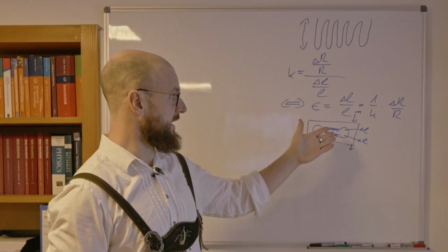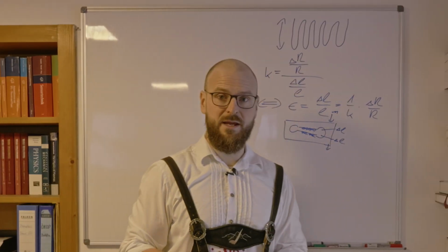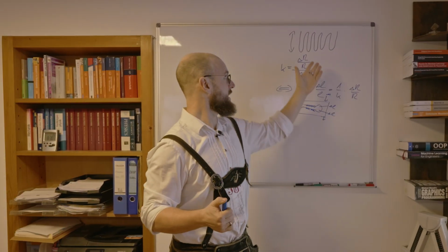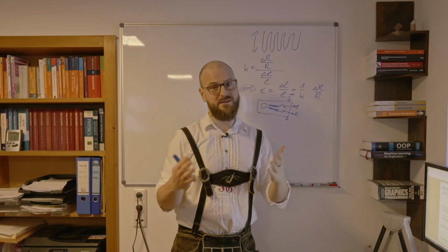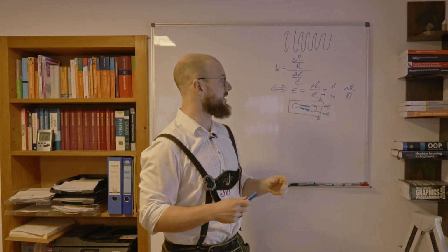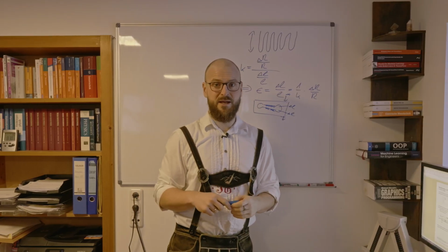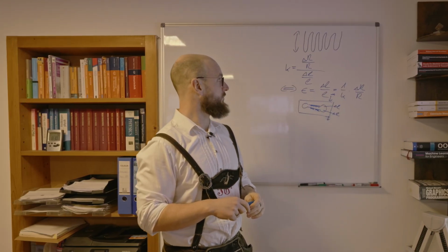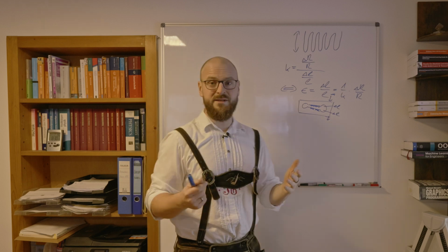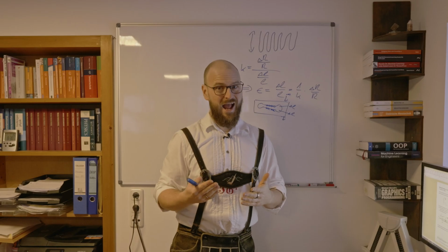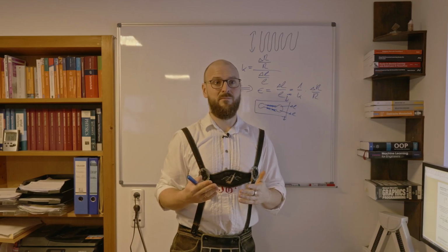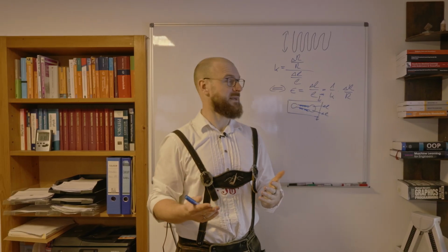For sure, as I said, you can place strain gauges wherever you want to. The simple way of applying such a strain gauge is just gluing it somewhere. That's the typical way of doing so. So even the application of that strain gauge is very simple. And moreover, they are very stable. So they keep working and keep working, and they can be driven with high dynamics.